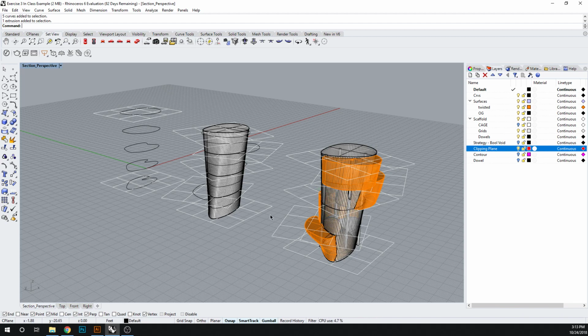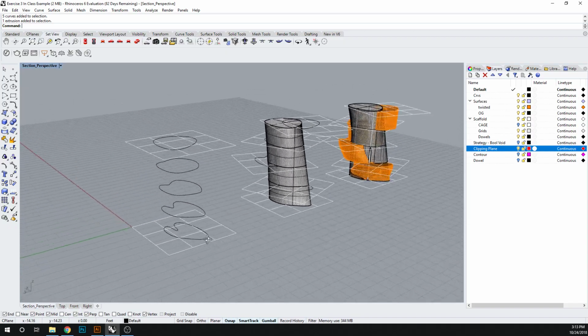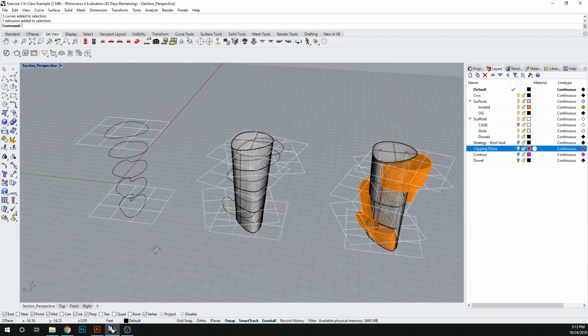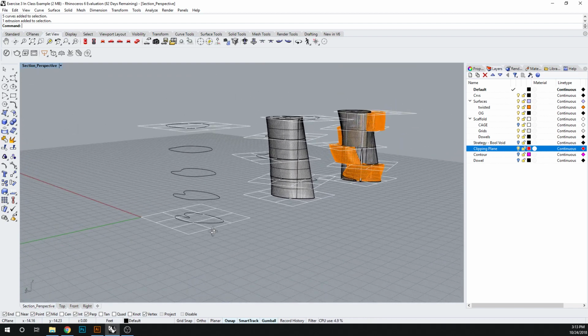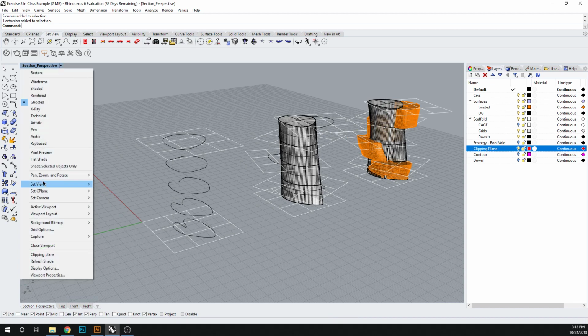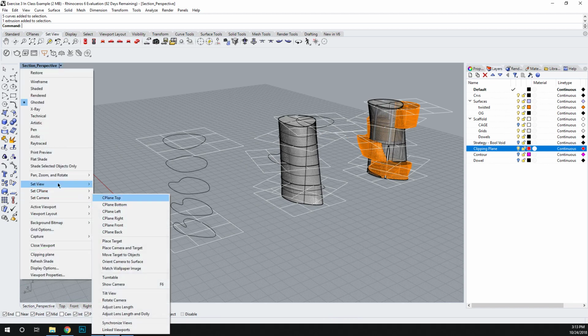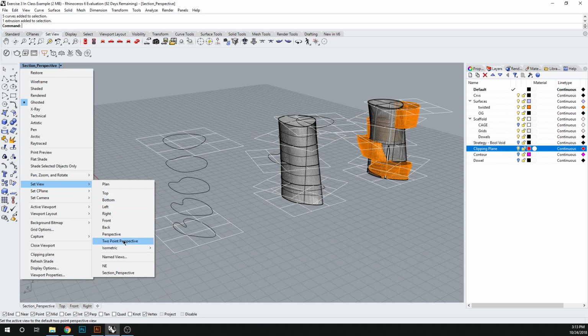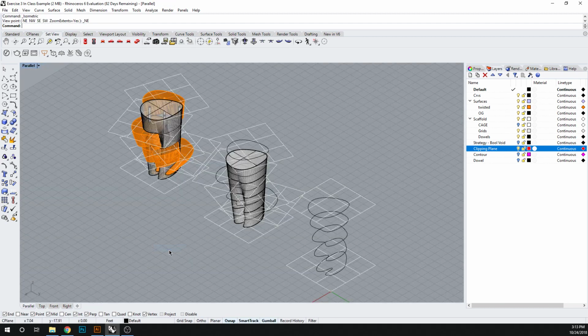Okay, so the first thing I want to do is go over a variety of ways of using the Make2D command. For one, Make2D requires a view. So let's find a good view for our first set of drawings. I'm going to change my camera and set my view. I have a variety of types of views. We are currently in a perspectival space. Let's change it to an isometric space. So why don't we go to the northeast here.